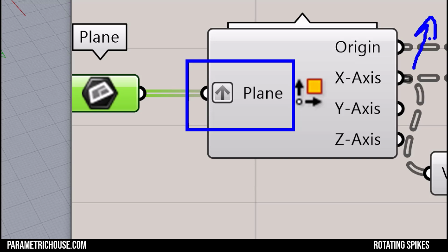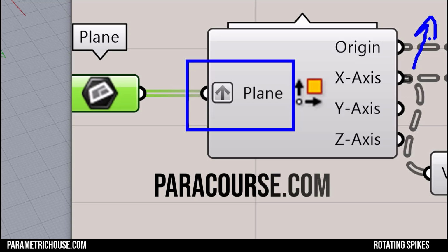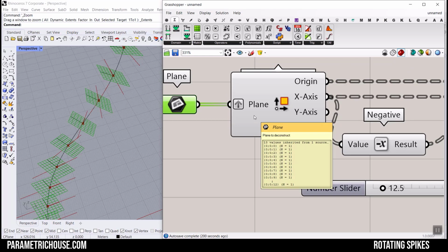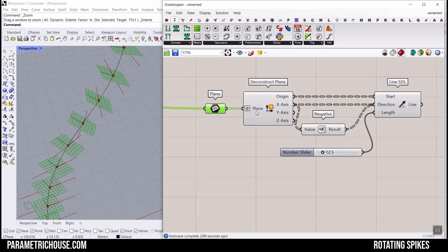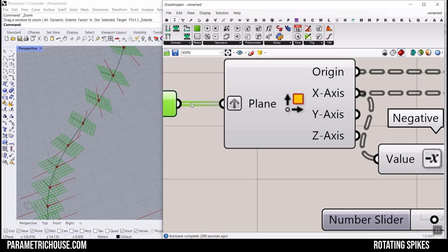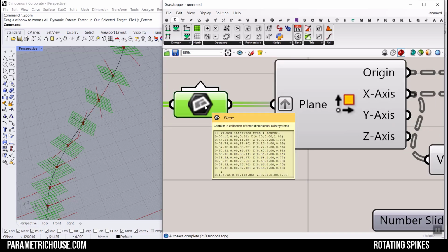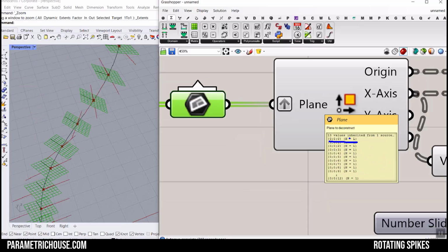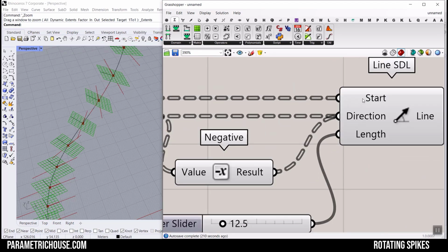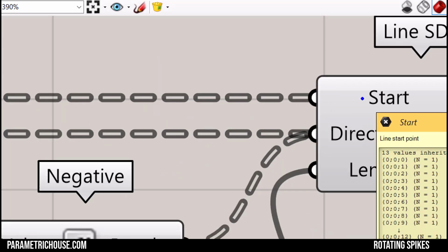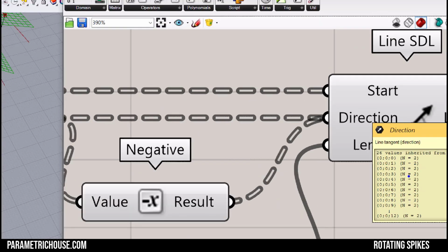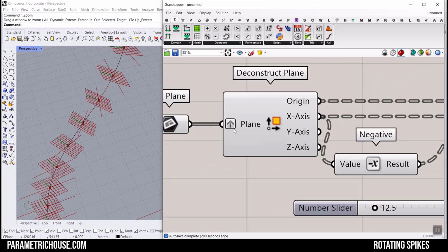We have also a complete section for the Power Course users, in which we have talked about groups, because obviously a programming language with geometry is a little bit hard to understand, so you have to understand what's happening here. So you have 13 planes, then you graft it, so each plane becomes a group. When you use that, you can see that it's going to have 13 groups for the start, 13 groups with 2 inputs, which is 2 directions. So that's the trick we used by grafting the inputs of the plane.